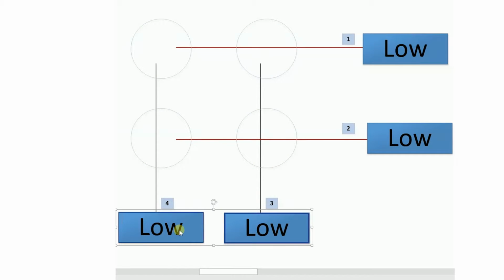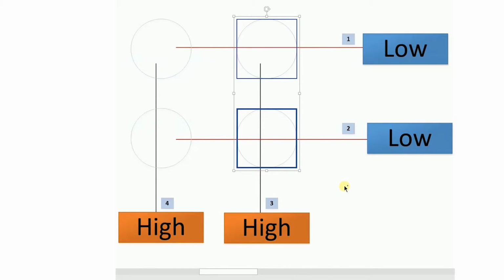And I set all the columns to high. So, in order to light up an LED, the anode pin needs to be high and the cathode pin needs to be low. This is the exact opposite, so we're as far away from on as we can be. So, we want to light up these 3 LEDs and leave that one off. So we're going to do one column at a time.